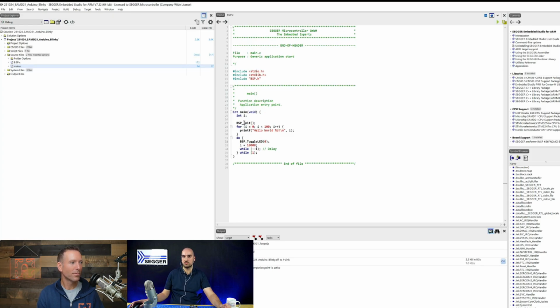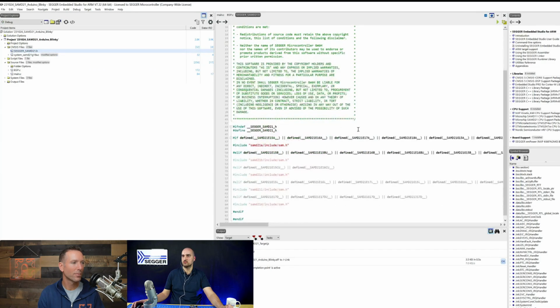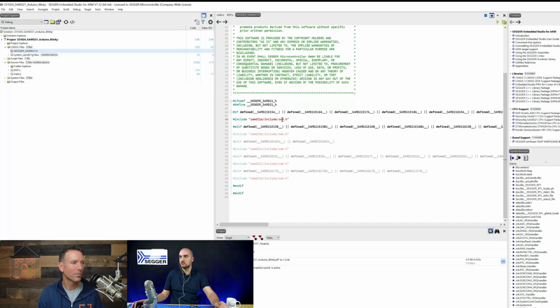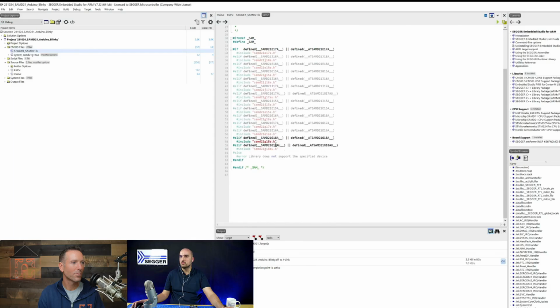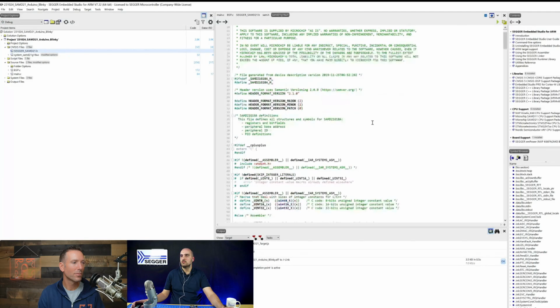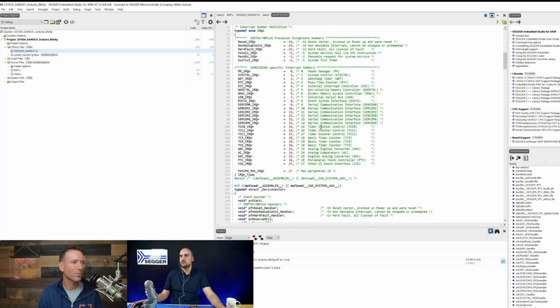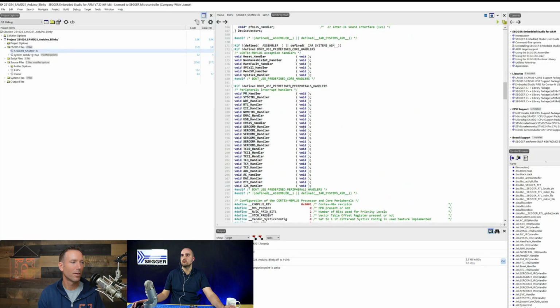But to make life easier, a lot of silicon vendors also provide parts of these drivers for chips. And there's also, from ARM at least, a standardized CMSIS interface. It's a Cortex-M system file, something like that. It's essentially a standardized interface which gives you a header that defines the whole CPU. So if you go into this function in this header and go to the header from the CPU, you'll see that it defines all kinds of things that can then be called from your main function.